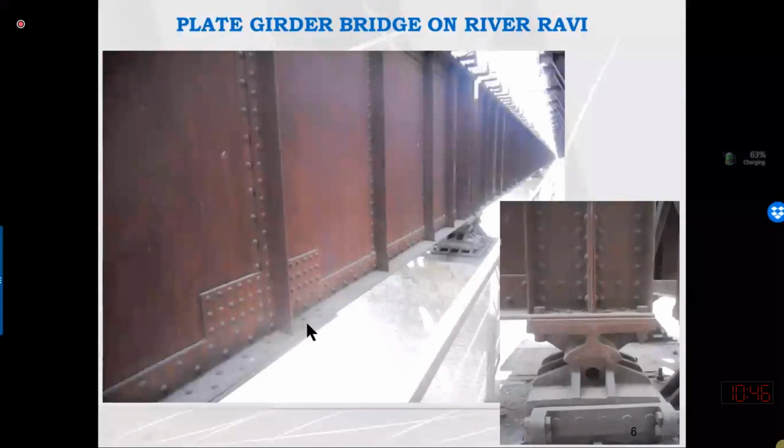If we require the thickness of the flange very less, the angles may be served as flange plates. So there, this projected leg can be used as a flange. And here you can see an extra plate is also welded to increase the thickness of the flange. Why it is welded, I will explain in the next slide.